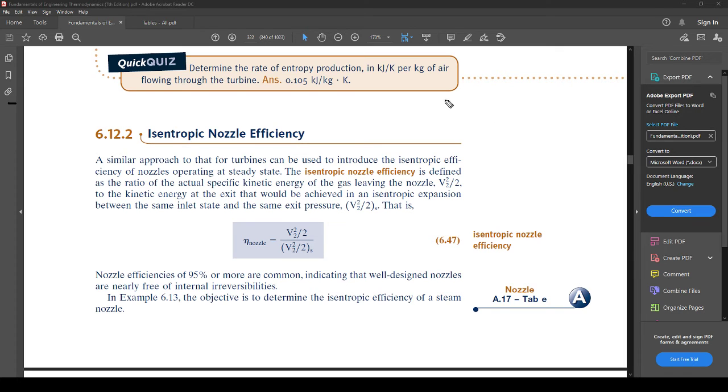Essentially what it is saying is the following: in this nozzle, which I'm going to draw right here, this is the nozzle. When it comes out this side at V2, which is velocity 2, what do we want out of this? Out of a nozzle, we want the velocity. That's the important thing, just like a turbine, we want the work. We want velocity 2 because that is what gives us our thrust, for planes, for jet engine cycles.